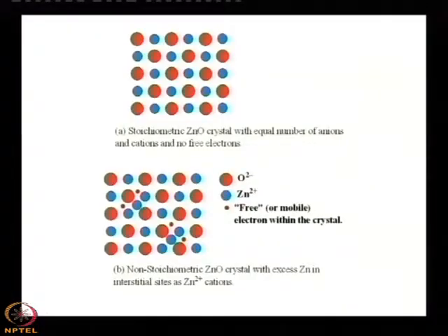Here we have not used any doping or impurity, even then it is n type in nature. Similarly, lead telluride, PbTe, is p type in nature. It is because of the non-stoichiometry, which is obviously a defect, and this has given you the advantage that without doping it is n type in nature.